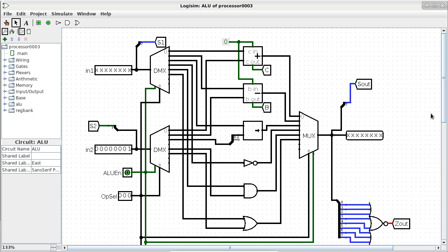So now we have these boxes in the inside here that can perform different operations. So we have an adder. This is an adder. If you click on it, it will tell you what it is. This is a subtractor. So with a subtractor, we have X, Y, B0, B8, and D. Those are the letters that we used when we talked about the carry look ahead and the borrow look ahead mechanisms. This is a bit shifter. It allows you to bit shift to the right-hand side. There's no left shift.